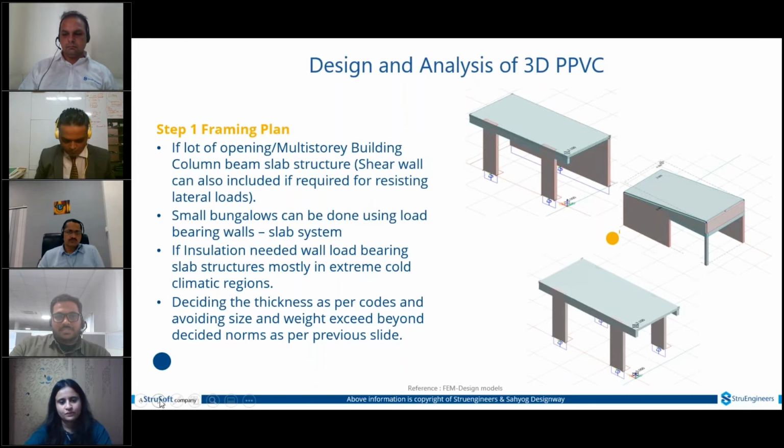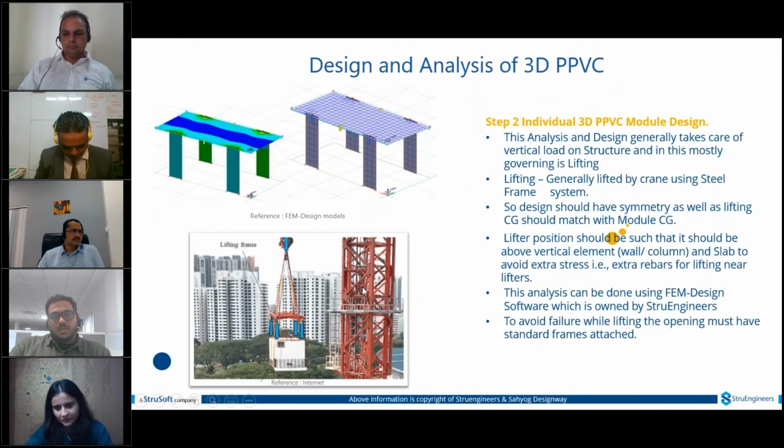After that, the second step is the individual module design, where every load, vertical load, lateral load is actually taken into account. But the governing part here is lifting. For the lifting part, we have to design how it will be lifted on site and in the manufacturing unit.